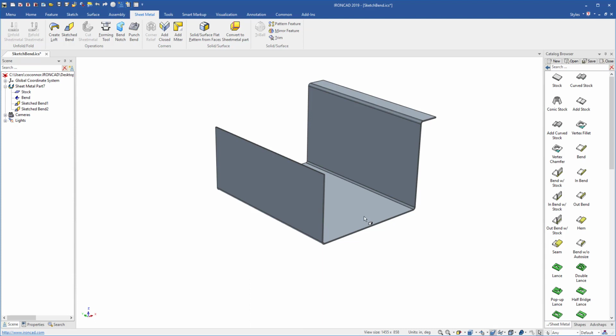Keep in mind you are designing in flat, so if you add multiple bend lines to fold a sheet metal, all the bend lines will be on the flat pattern, not on the actual bends that are resulting. The cases I gave you actually were the single bends, but if you had multiple bend lines, they would appear on that sketch plane and you would have to reference the sketch itself. But it is a very useful feature if you add multiple sketch bends to drive them sort of like you do your regular bends. Hope you enjoy.